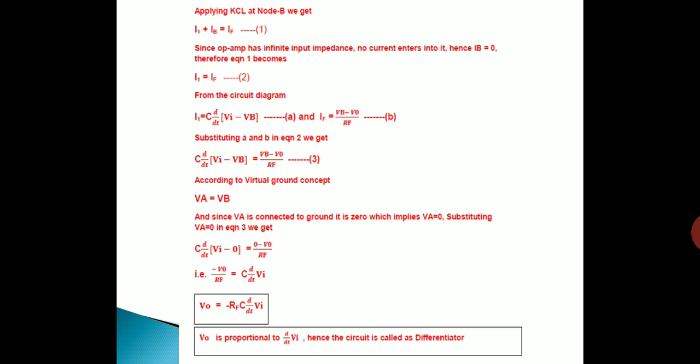Now rearrange the terms in this equation. You get minus V0 by Rf equal to C into d by dt of Vi, or V0 is equal to minus Rf into C into d by dt of Vi.